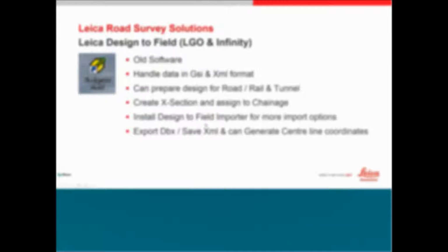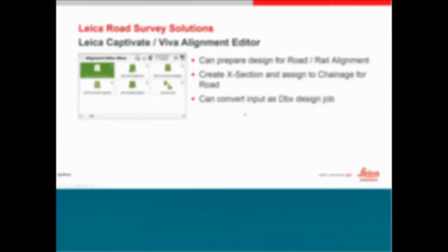When you have to use Design to Fill, you may have to install the Design to Fill importer so that you can take in more import options, different types of data files, and export DBX or save into XML format and use it on board the instruments. Okay, this is the Leica Viva or Captivate's alignment editor, as I have mentioned earlier, for input of element by element.